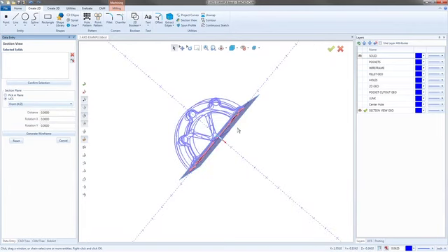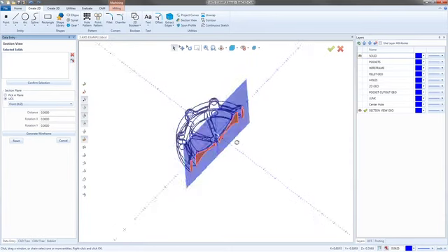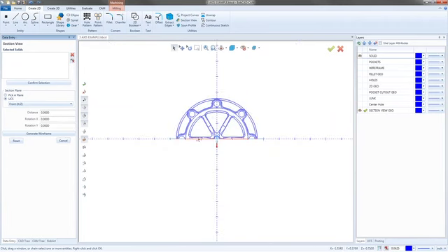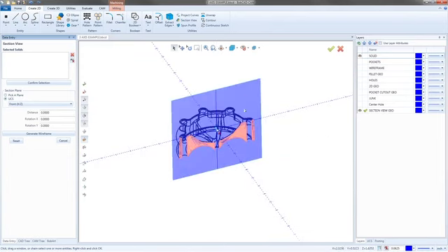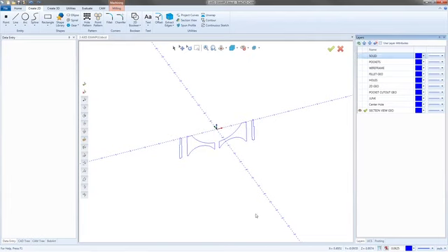But what it does is if your part is centered, like I have it here, my part's perfectly centered on XYZ 0, I'm actually able to come in, and it just so happens with the way I set my part up, one of those edges, so one of these walls right here runs right down the XYZ 0. So this plane that it's creating, this section view plane, is splitting my part perfectly in half. And so what I'm able to do is I could come down here and say generate wireframe and then cancel out and then turn off my solid, and I'm left with this geometry. That's the geometry for, well, what I just pulled off from that section plane. So what we saw in that section plane was what we were able to pull off.